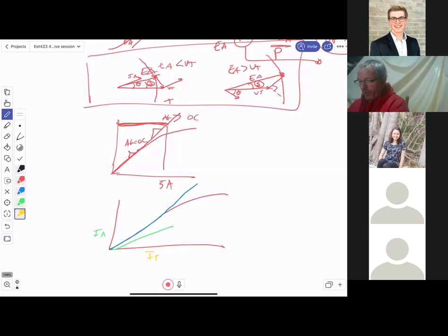You know you're saturated at this point right here. You can see that it's starting to curve away from a straight line. If the magnetic material is unsaturated, it's going to stay linear. It only starts to become nonlinear when it saturates. And you can tell saturation because the air gap line is linear the entire way, while the open circuit characteristic is nonlinear, it saturates.